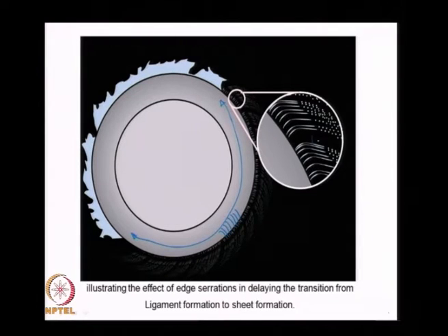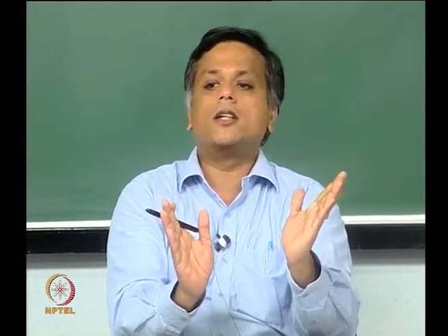Okay. By controlling the RPM, I can control the cone angle of this spray. So, the angle over which the conical sheet that is spilled over the lip is at.